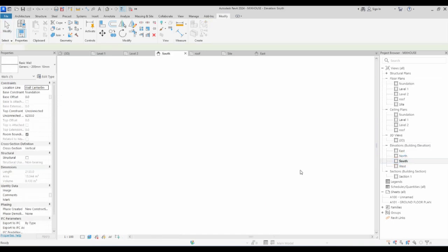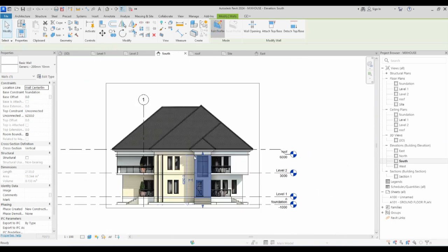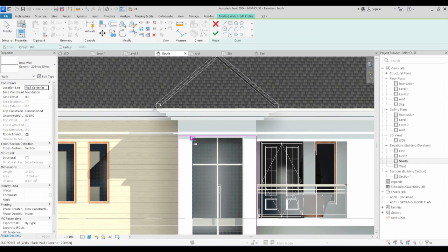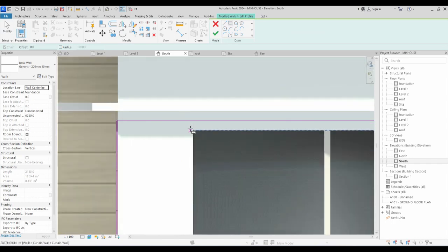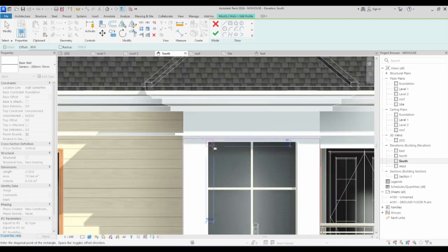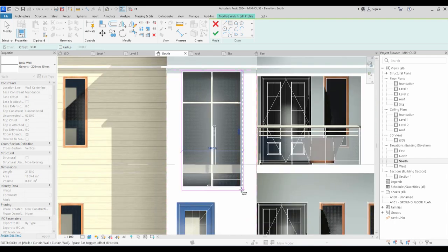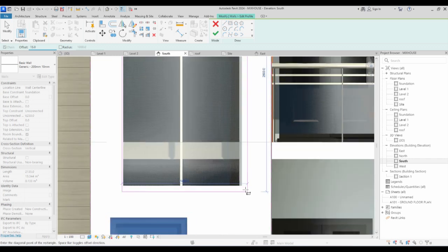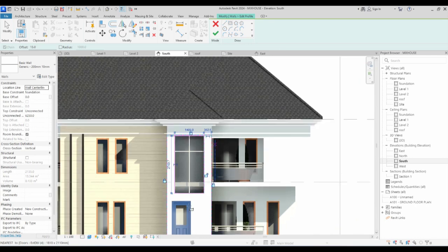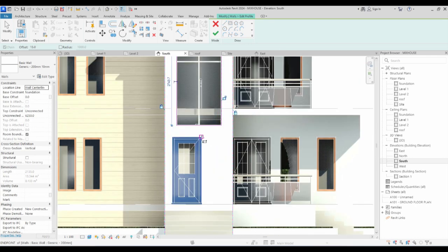So you can select this one and change this entirely. Go to south elevation. In the south elevation, you can provide and you change it entirely. So select the profile. Because of the mullion you put from outside, let's say you select the offset here, let's say the mullion is 30 mm, so you select from that. So that's going to take that out of it, take care of that. So if 1330 is too much, let me use 2015. So you take care of that externally. So you click OK. The same thing with the wall as well, and do them together instead of doing them separately. And you say OK.